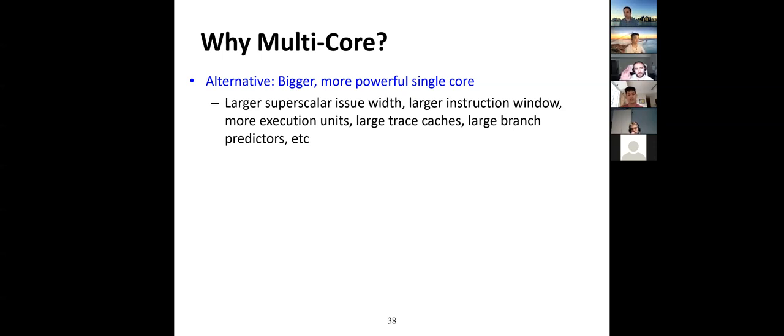Okay. Pavel? You'll need the n-squared bypassing logic, and the read-write ports on the register file. Those are the ones I can think of. Read-write ports are still less of an issue, although it is an issue. Okay, I'll give you a hint and try to think about it. Most modern processors are out of order. So what makes it complicated if I have to deal with a large instruction window when I do out of order?